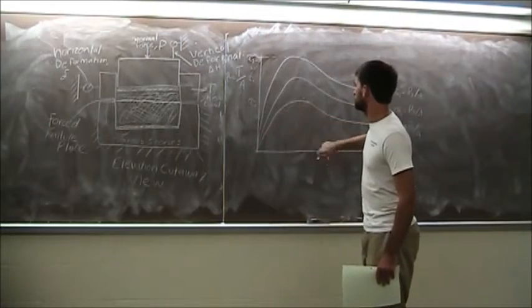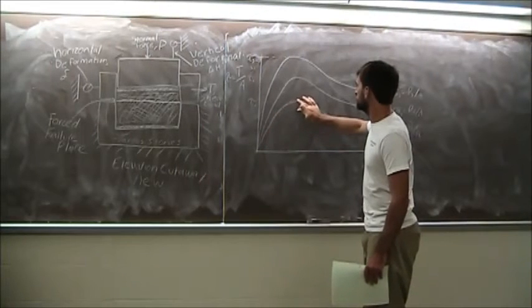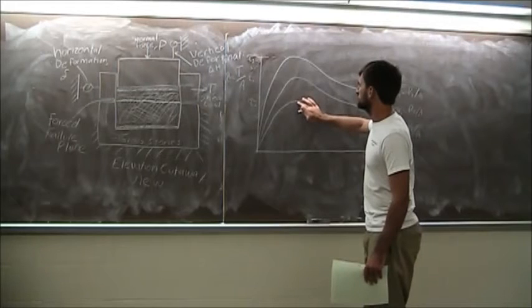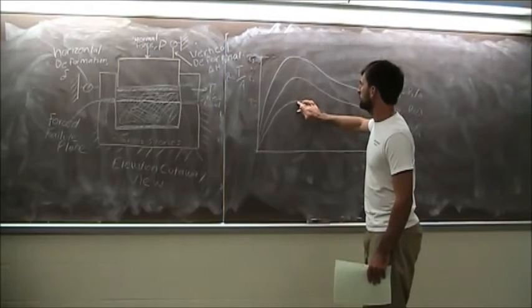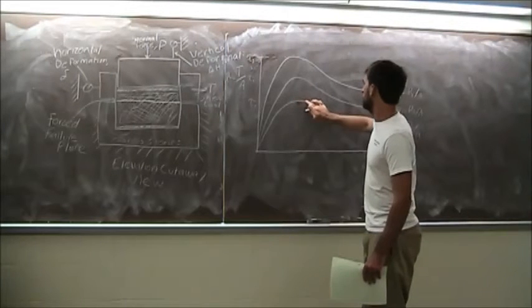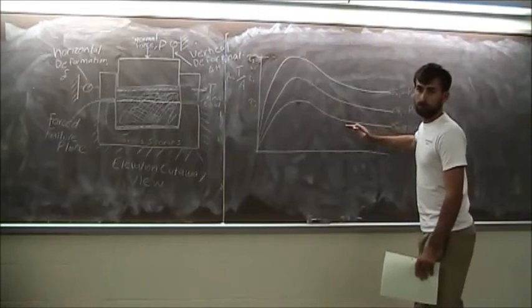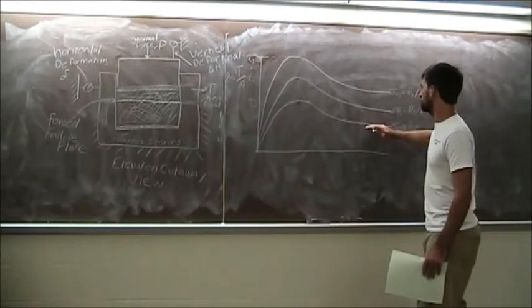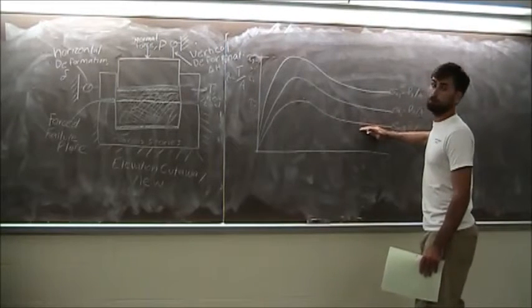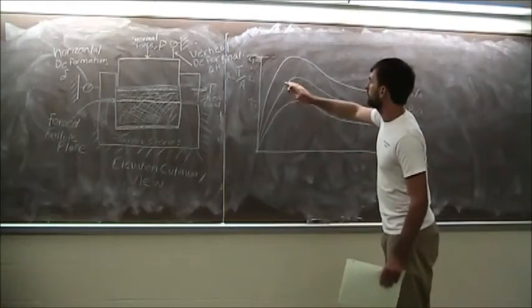We're getting a little bit of displacement, but it's not a whole lot. And then once it hits this peak, that's kind of like your peak static friction, and then it starts to move a lot, and then it drops off, and you have less strength, and that's just like you have less frictional force because you're now in the dynamic mode where things are moving.